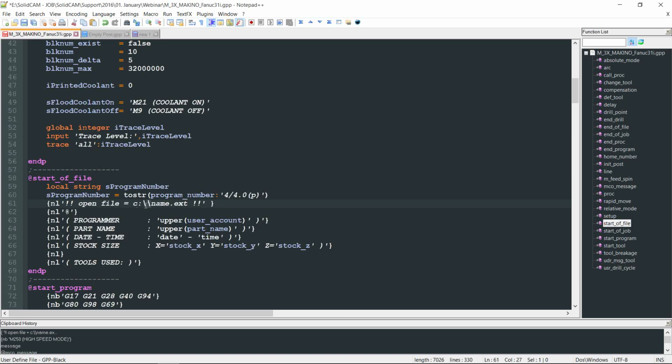And what I will do here, in the GPP file, it's not allowed to use just one slash because it's coming from Windows. Internally, it needs to be 2 slashes, and then the Gcode, right? The specific folder, 2 slashes, and now our Gcode file name, how I would like to call it.